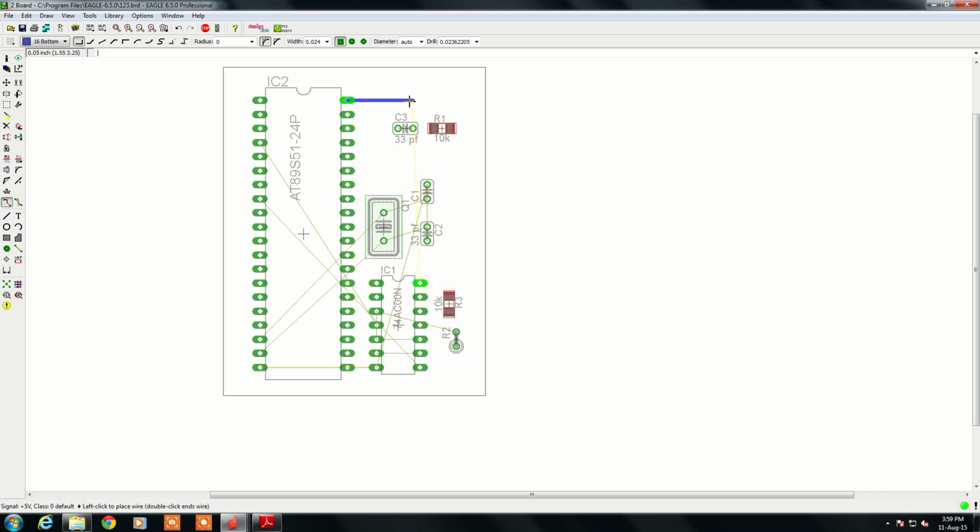If I start from here, now you see this width is approximately 24 mils. Whenever I change the direction, you can see it is changing at a right angle. But in layout, never use a right angle, because there is a possibility of hairline cracks. So use a slight inclination, a wire bend style. Now if I change this side, it will bend. This color is blue, which means this is the bottom side of the PCB. Now this completes the starting point and ending point of my copper track.